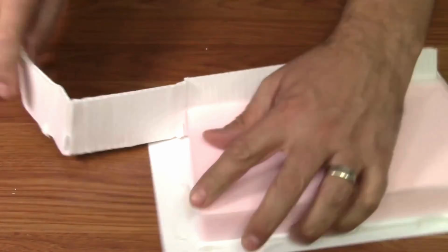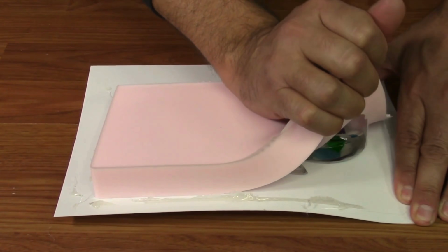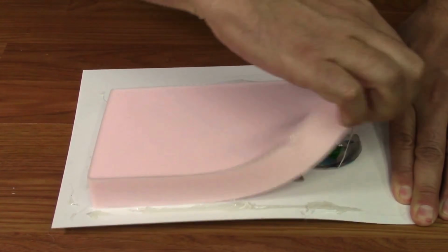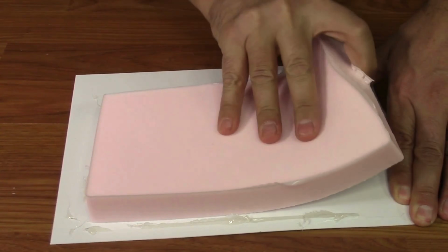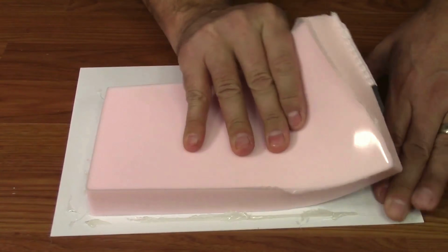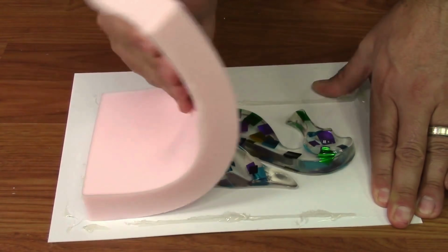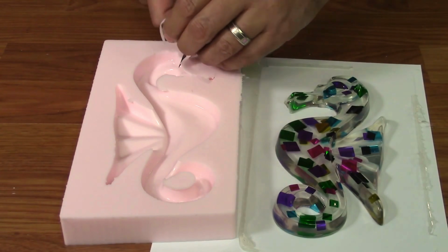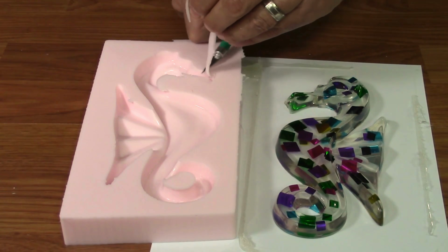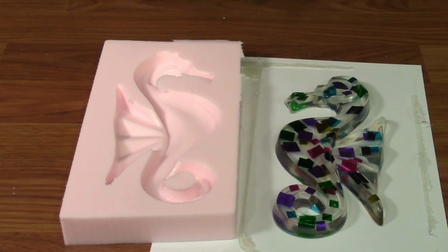Once cured, the silicone block is sectioned along predetermined parting lines, allowing removal of the master while preserving a highly accurate negative cavity. Registration keys are incorporated into the mold halves to ensure precise alignment during subsequent casting operations. Proper vent design, gate placement, and mold geometry are essential to minimize trapped air and facilitate complete filling of complex cavities.